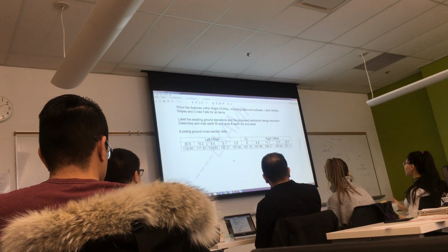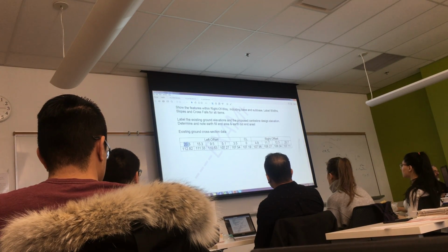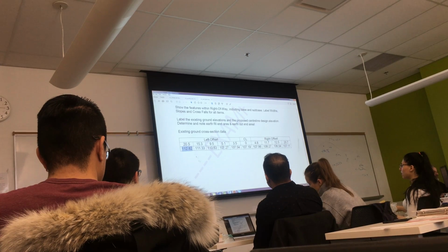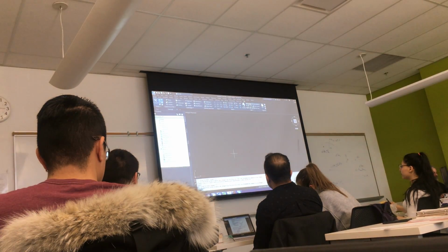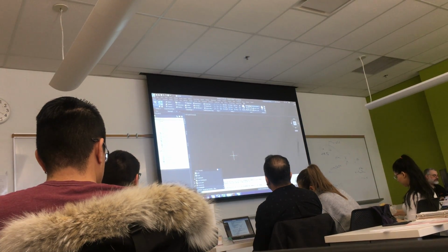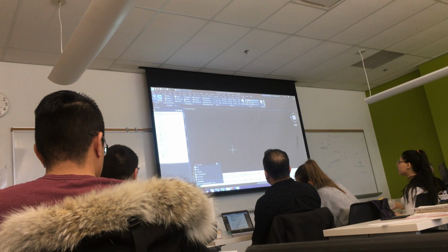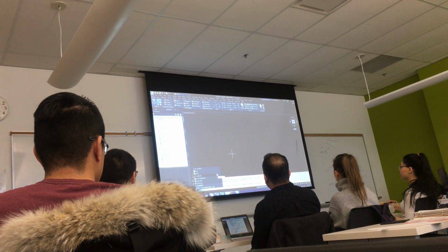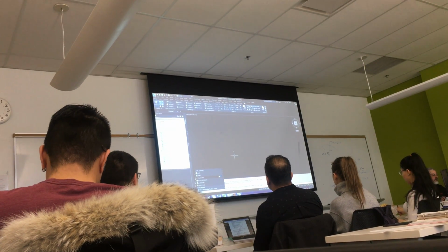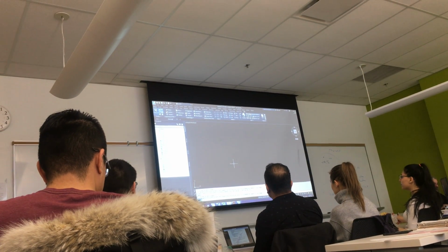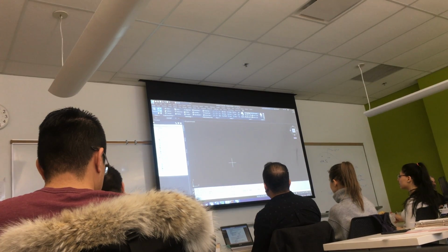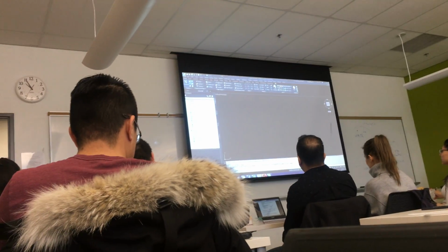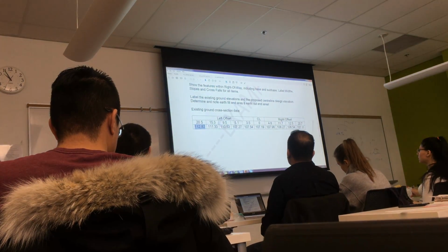So if I wanted to draw this, the first point would be negative 20.5, 112.82. So if I go to AutoCAD, I'm going to draw a polyline. PL for polyline. I apologize for the small font down here. That's why I'm just going to give it to you orally. I'm just going to talk about what I'm doing. Okay? So polyline command. PL for polyline. And I'm going to type in that coordinate. So the coordinate is negative 20.5,